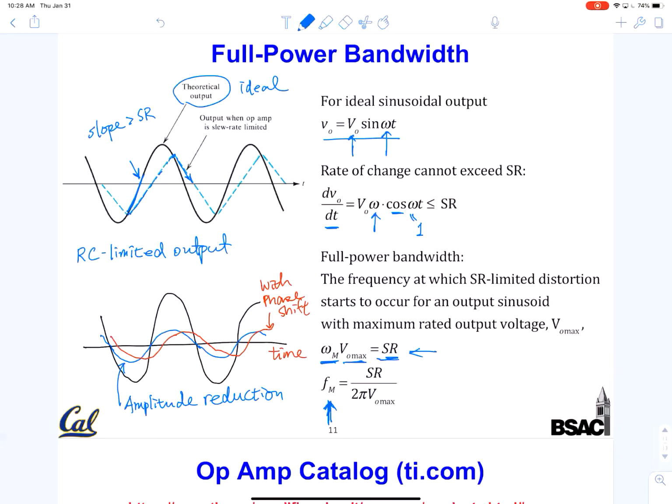If you pick up a signal, yes, you have a voltage, but it's not high fidelity of the original input. Well, you're more than picking up the signal. You are picking up distortions as well, and we try to minimize that. And are you sacrificing anything if you're increasing your slew rate? Yes, you always do. If you pick an op-amp with higher slew rate, yes, you always sacrifice something. And you have to look at the whole spec.